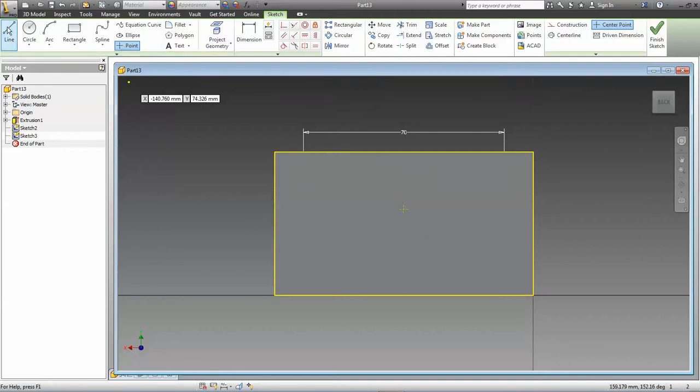I can use the line command, and this triangle starts 10 millimeters in from the last one. Click there, so that's minus 70, and I guess that's 50 or minus 50. Click there, click down on the work point, click back up at the end. Okay, and again, escape to get out of the line command.